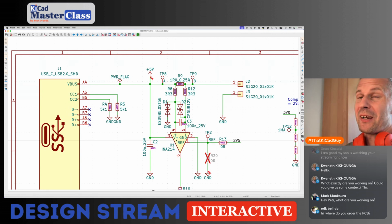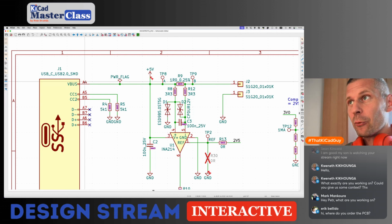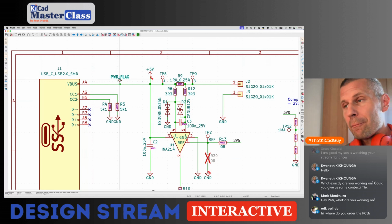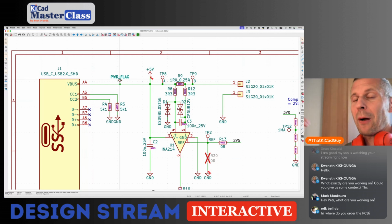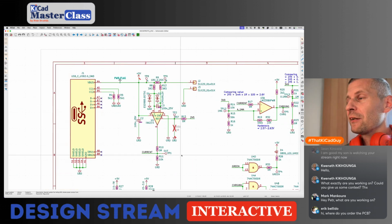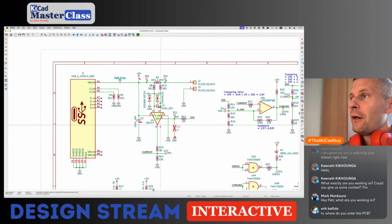So this power input pin expects a power output port, but this is not a power output port, this is a passive port. So when you place the power flag here, it marks the net as providing power for the power input ports. And the same is with the ground.